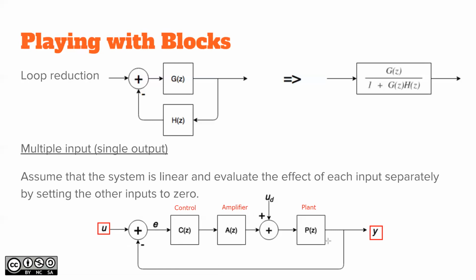Okay, so that's a simple controlling loop, which tries to minimize the error. Same as the negative feedback on an operational amplifier. The operational amplifier with negative feedback has nothing else to do than try to keep the error, or difference between the inputs, as small as possible.